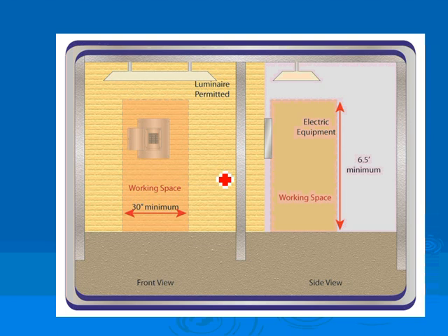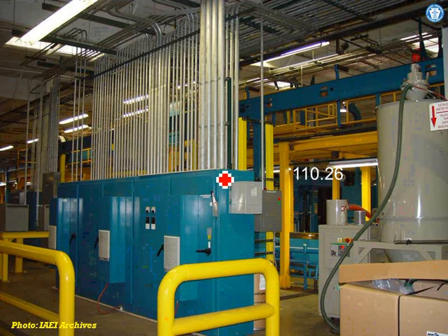And there are rules for large electrical equipment, 1200 amps or more and more than 6 feet wide, then you start doubling the distances between them or having 2 entrances and so forth. So this is strictly, guys, to give you access to electrical equipment, to work on the electrical equipment energized.